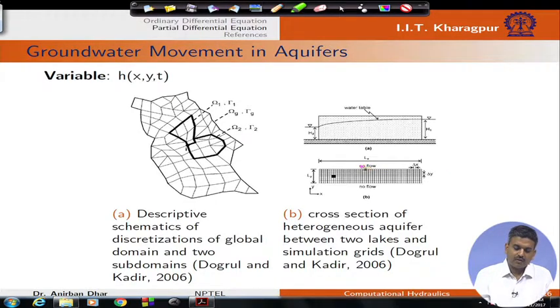Let us say it is constrained by no flow condition within this Ly distance, then your problem gets slightly modified, because we need to consider the Qy component here along with Qx, and if your H2 and H1 values are not varying, then we can get a steady state situation, because there will not be variation of water level within the system.